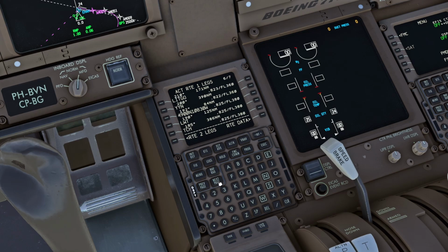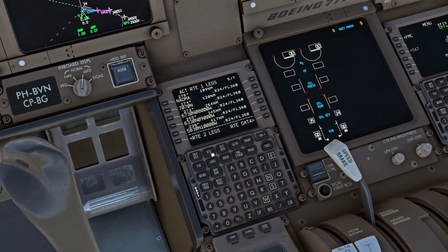Basically you just cross-check through the flight plan and make sure that all the waypoints are in there. Now, of course, you could also type in the route manually if you want to. It takes a little bit of work. You can do that here via the route page. You can simply enter the airways and then it will automatically recognize where you go onto another airway. Or if you have a direct, you can also enter a direct.